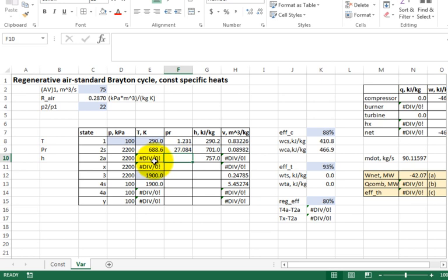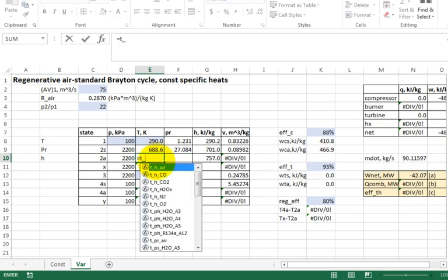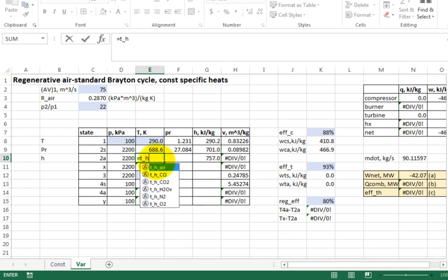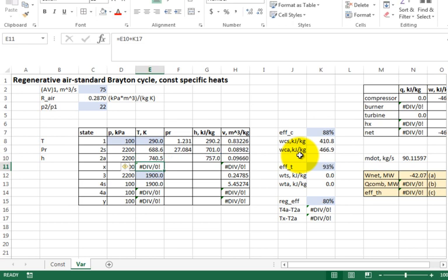But we would like to calculate the temperature. So it's equal to the temperature as a function of enthalpy for my air. Again, you go into the table, and now I know the h's and I want to interpolate to get the T's. All right, and then close the parenthesis and done. Okay, state X we have to avoid for a minute. We have to go down here.